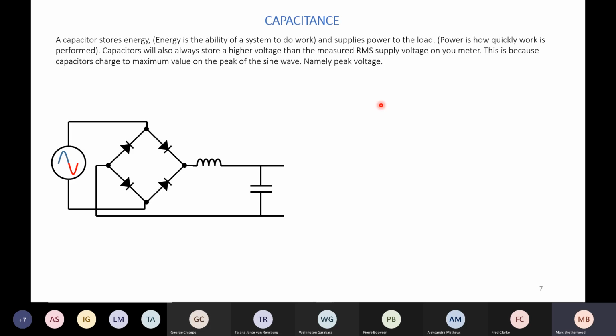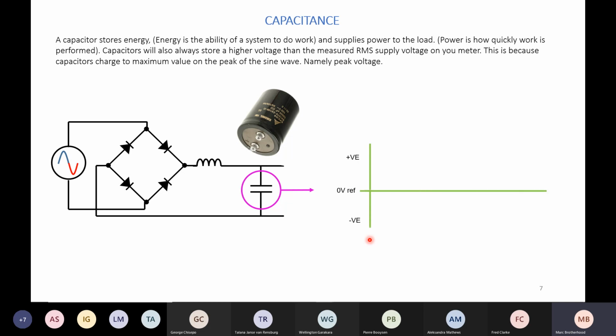If you open a circuit at home and you want to be brave, you see the bridge, and you'll see your supply capacitor. That's what it looks like. You put your meter on there. If you put your meter on AC, you're not going to measure anything. Why? Because remember, we're DC now. So you've got to put your meter onto DC, and you're suddenly going to see about 320 volts across these pins. And you say, how's that possible? You put your meter on AC, and you're only getting 220 volts in.